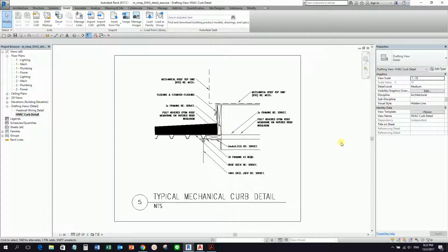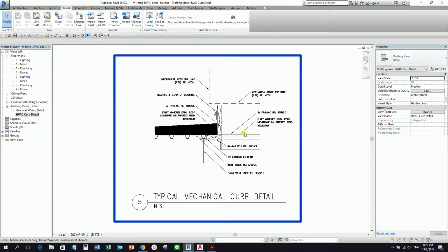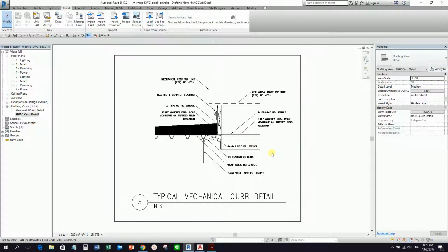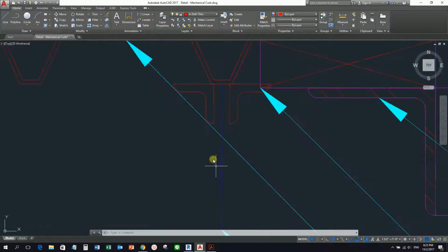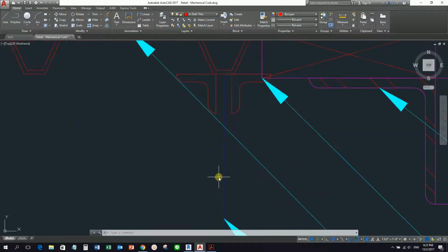Now what I'm going to do, I'm going to edit this one. So notice that the leader lines in the AutoCAD file retain their defined line weight when imported to Revit. Before importing the AutoCAD file, you specify line weight 4. Remember? I changed that to line weight 4 for elements on layers with blue color. So if I go back to AutoCAD, you notice this is my blue color.